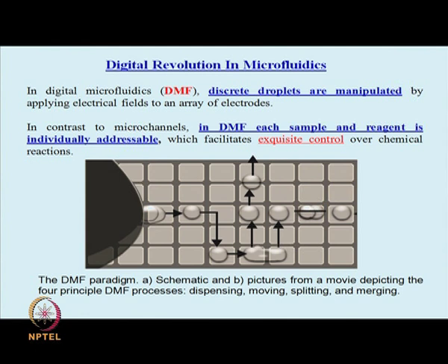So, what you do is you switch this electrode on, while the other electrode is switched off. By switching it on at the right voltage for the right amount of time, a small droplet can be spliced from the larger pool of liquid, and you simply get one droplet, and then the droplet is made to move on the electrode surface in a specific direction. The direction of the droplet movement would be governed by how you are switching the electrodes on and off.